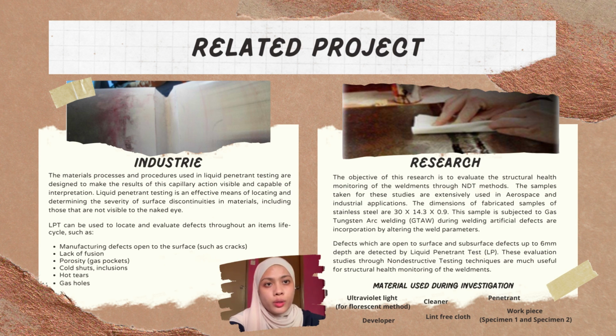The profile of weld defects is studied using basic non-destructive testing techniques. Defects which are open to the surface, and subsurface defects up to 6 mm depth, are detected by liquid penetrant test, LPT. These evaluation studies through non-destructive testing techniques are very useful for structural health monitoring of the weldments.